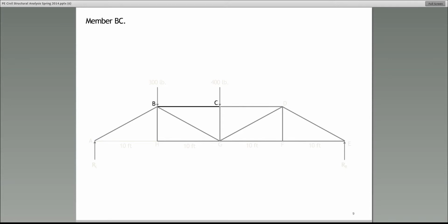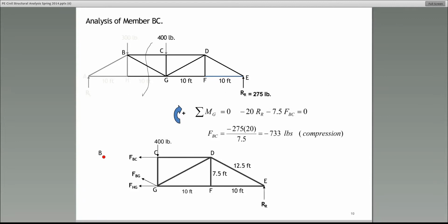Let's do it. When we use the method of sections, what is it that we do? Well, basically, we cut the truss at a given section. Here, that would be the section that I would use. In other words, I'm going to cut through BC, then the diagonal and the bottom chord. Let's take a look at the next slide. All right, so there it is. Please take a look at the top, and this is the section. It's a vertical section, so since we are looking for the force in member BC, BC should be one of the members that we cut. All right. So there you go.